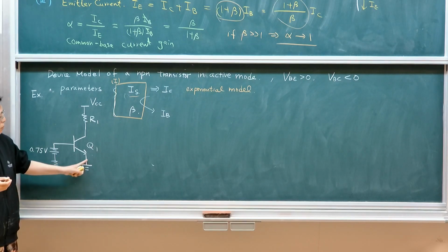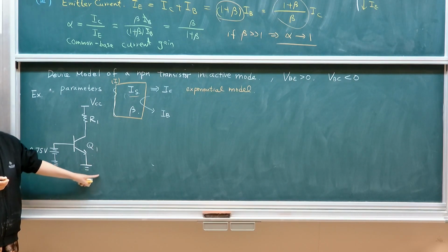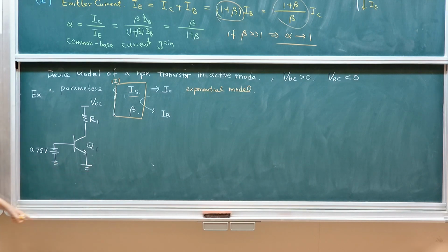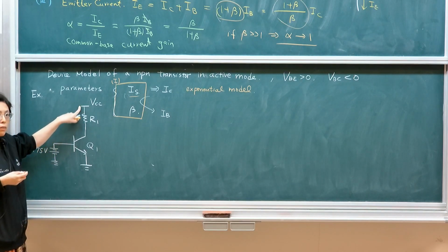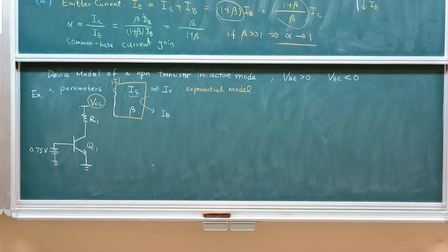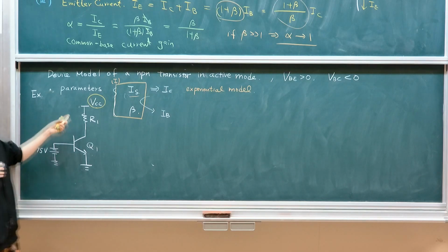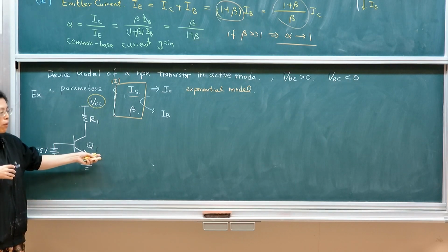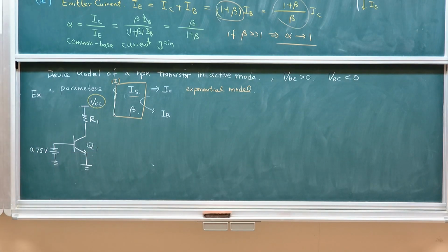This is a common emitter structure. Remember, my emitter is grounded. Ground is typically referred to as the common node, meaning that it does not carry any signals or biasing. Your most positive voltage is typically, we're using the convention of VCC. C stands for collector. Therefore, VCC is because it's a BJT circuit. If we're using MOSFET, it will be VDD. So this is just a convention. And as I said, if you're using bipolar, you're using Q to indicate that it's a bipolar junction transistor.